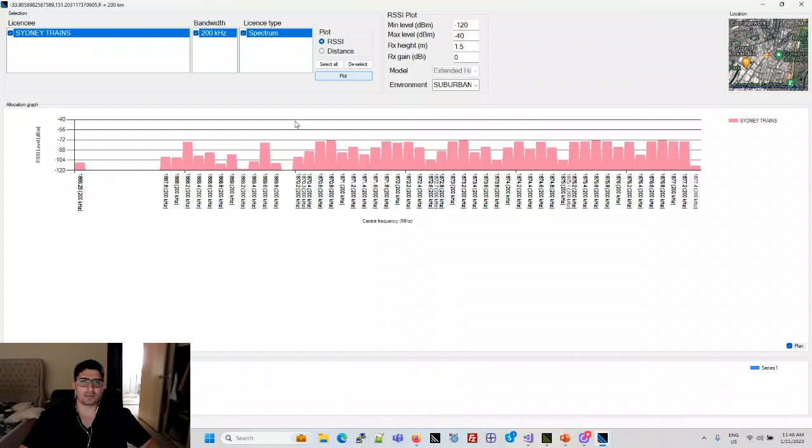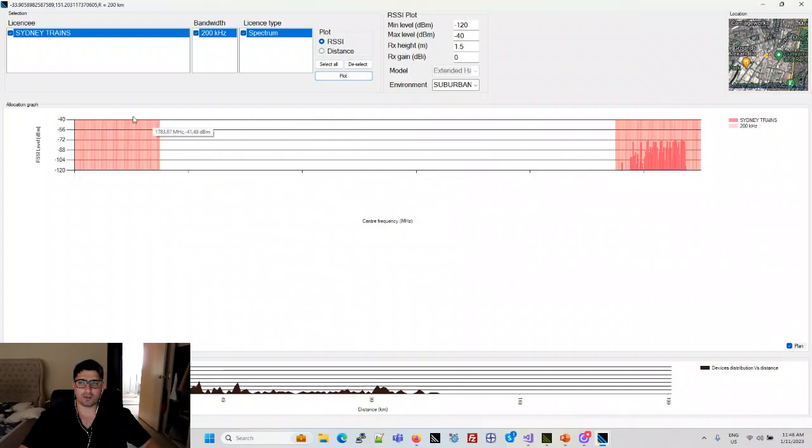So go plot, and then you see very clearly now you've got uplink band and downlink band. And the uplink band here obviously is empty because we remember the query that we ran was really limited to transmission type ports or devices. So that's why these are not showing, because these are of type R. These are of type T. Another reason is because they've got no power level over there, so it would be zero power level. Whereas here we have 83 watt ERP or 8.3 or something like that.